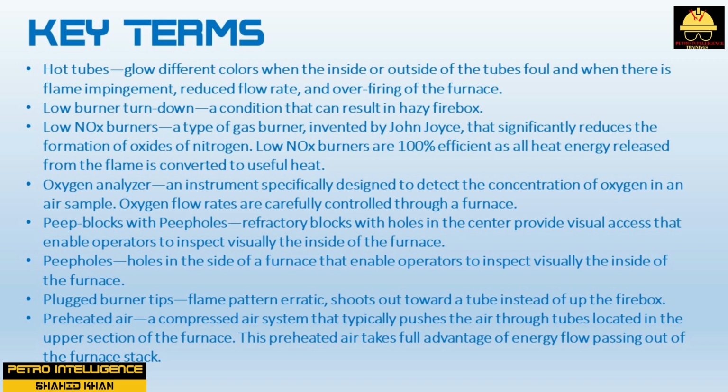Hot tubes glow different colors when the inside or outside of the tubes foul and when there is flame impingement, reduced flow rate, and overfiring of the furnace. Low burner turndown is a condition that can result in hazy firebox. Low-NOx burners is a type of gas burner, invented by John Joyce, that significantly reduces the formation of oxides of nitrogen. Low-NOx burners are 100% efficient as all heat energy released from the flame is converted to useful heat.